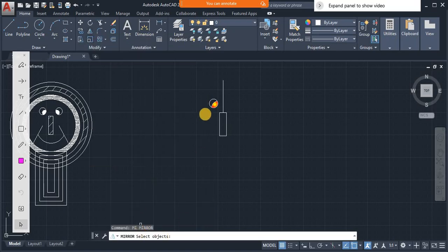Now it is asking select object. So I click on the screen, then move the cursor towards right and then again click. Now the objects lying within this window have been selected, you can see here specify opposite corner 3 found. So 3 objects have been selected. Which one? This complete circle and this arc and the gradient which I have drawn. These 3 objects have been selected. Again it is asking select objects. No more objects, so press enter.